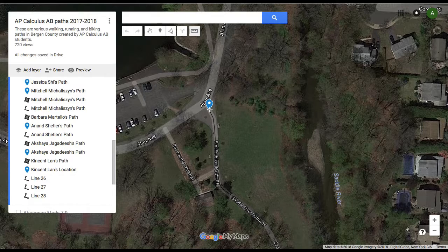So to find each point, I clicked on the marker to use that as my origin, drew a straight line along where my x-axis is, clicked again to make a point, and then extended out a perpendicular line to where it would intersect the path.